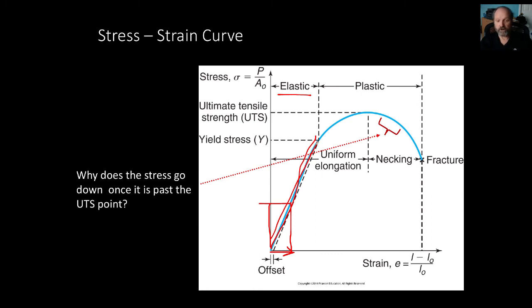If I go too far and I start to bend over, and let's say I go to this strain or stress, and I let go, it's going to follow pretty much this slope back as I release the stress on it, and it won't go back to its original length. It'll be some other length, because I went past the elastic region. So this is elastic.